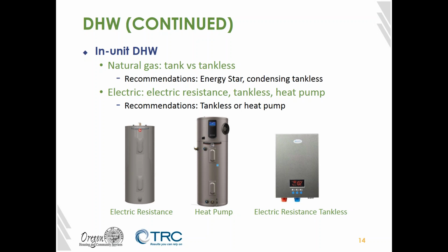It takes the heat out of the air and applies it to the water, so it needs to either be ducted or be in a space that has a lot of airflow. So you just have to be aware of that when you're looking to install these systems or recommend them. In terms of the actual energy use, the draw on the building, it's about on par with the electric resistance system, though.